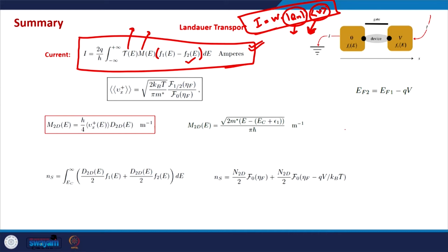But there is a situation in the MOSFET. If we plot the barrier profile, this is how it looks. This is the source side, this is the drain side, and this is the energy landscape in the MOSFET. More precisely, start from this side. It's very close to the source, and this is the point where the electric field is very small, and this is the point from where in a way electrons start their journey to the drain side, and a drain current is set up in the device.